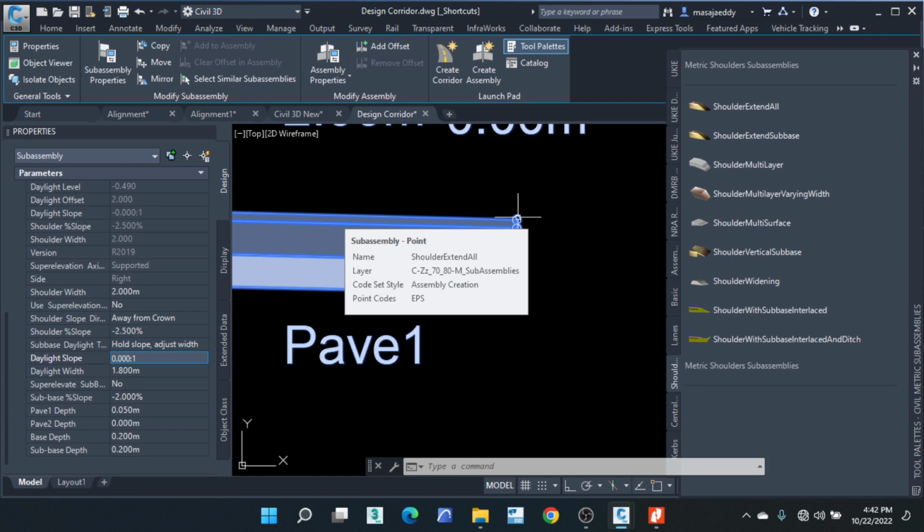How about if they continue with the same drawing that they are having? Would there be any issues? Not really, but the idea of using data shortcuts is to have a lighter drawing. Civil 3D drawings are usually very heavy when you're working with them. If you're having everything in one folder, it will be very heavy. Some people are still lagging behind because of the shortcuts. I was suggesting that those who can work properly can equally work with that same drawing, okay? It's okay. Okay, fine, thank you.